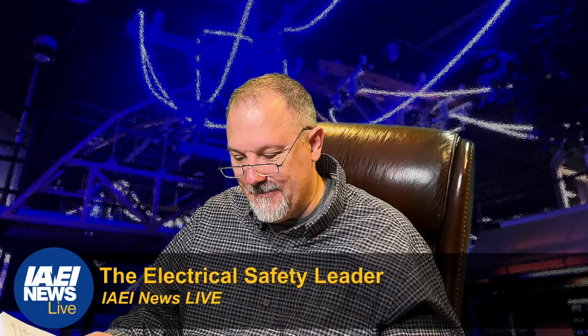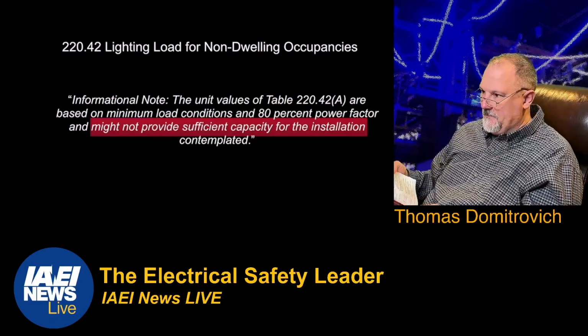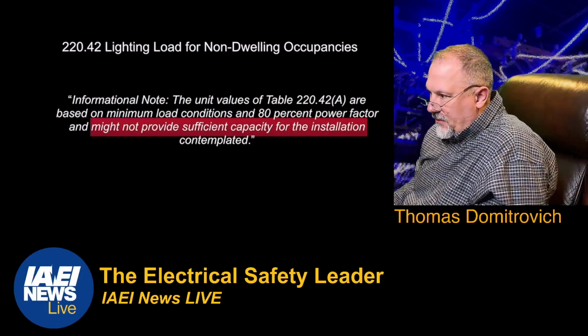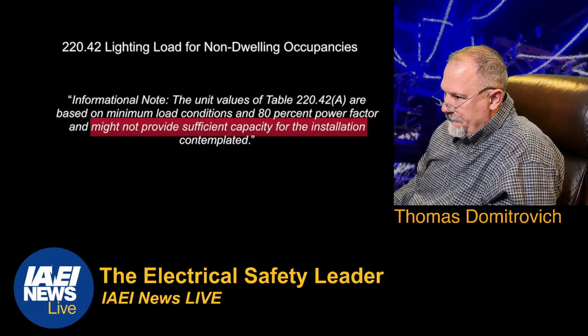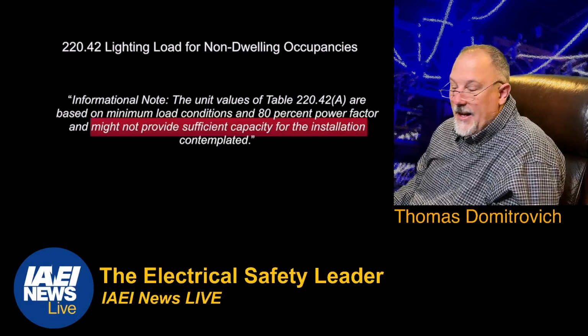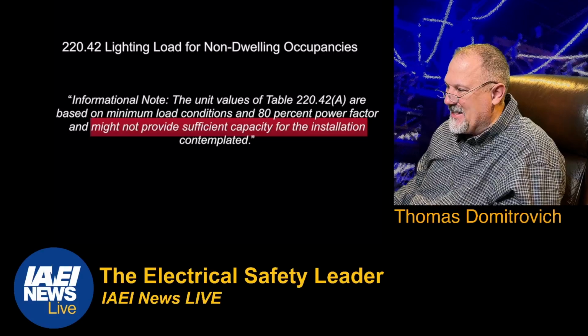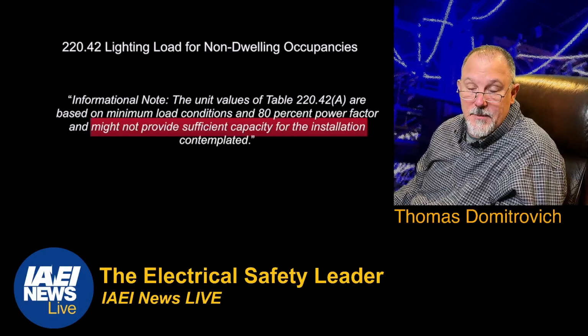And I love this. The unit values. There's a lot in this informational note. I'll take a look at this. It says the unit values of Table 220.42(A) are based on minimum load conditions and 80 percent power factor and might not provide sufficient capacity for the installation contemplated.